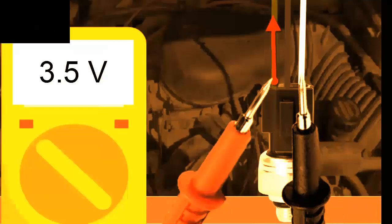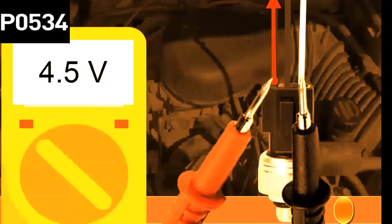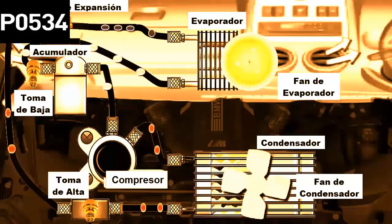E. Identifying the signal wire. The remaining pin or wire will be the sensor's signal wire. This should show a voltage value that changes when the air conditioning is turned on. If the sensor is on the high pressure side, its voltage will increase when the vehicle accelerates. If it's on the low pressure side, the voltage will decrease when accelerating. If the signal shows no variations, the sensor is likely damaged.